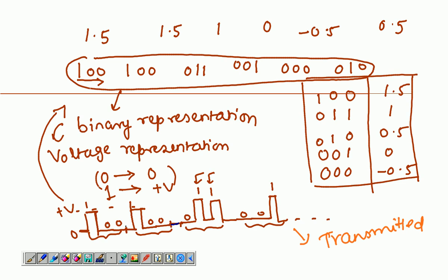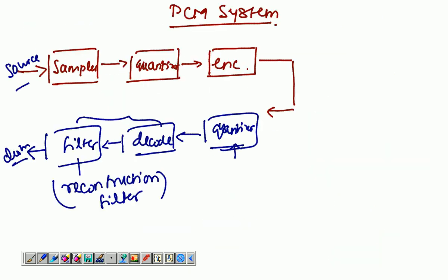So we need to minimize the bandwidth requirement of the system and still transmit the signal without noise, as a perfect replica of the transmitted signal. So when the bandwidth decreases, just imagine the signal shrinking due to low bandwidth, and all these gaps that we left for proper recognition of the signal start decreasing. And when the gaps reduce, sometimes the signals could just overlap each other, and the new signal could look something like this.